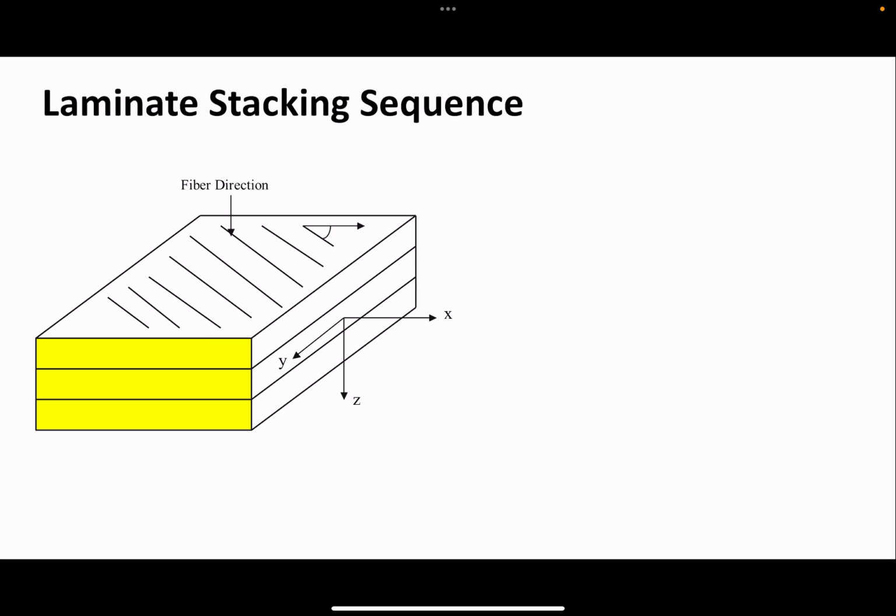It exhibits isotropic properties in the extensional stiffness direction, that is in the E1 direction. So it exhibits isotropic extensional stiffness properties. So when do you get this? This is a special case produced using at least 3 different ply orientations, all with equal angles between them. For example, 0 degrees, 30 degrees, and then 60 degrees.